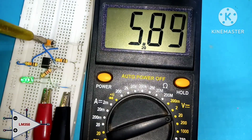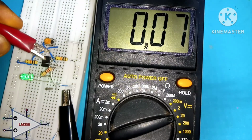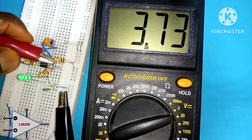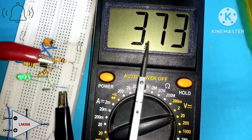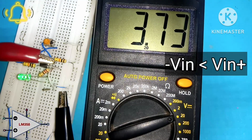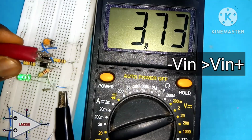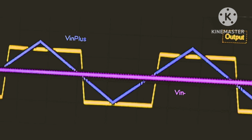Okay, let's take things the other way around. Let's see what our reference voltage is. So we're going to put that at the output of this voltage divider, and we see our reference voltage is around 3.7. So the output voltage is less each time our voltage at the non-inverting input is greater, and that voltage is greater if the voltage at the non-inverting input is less. And you can also see those signals displayed on the oscilloscope.